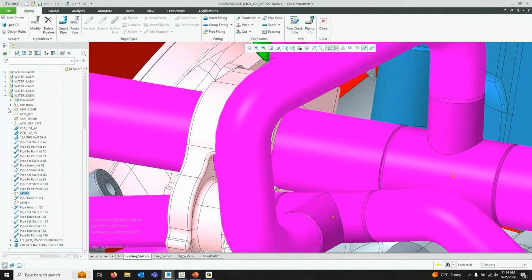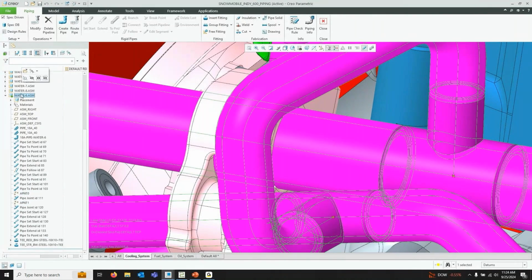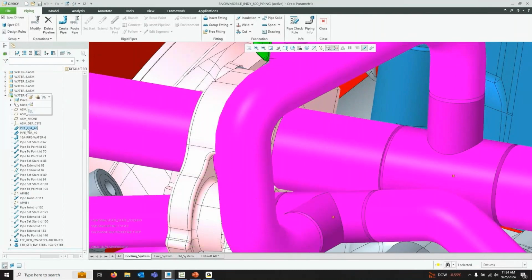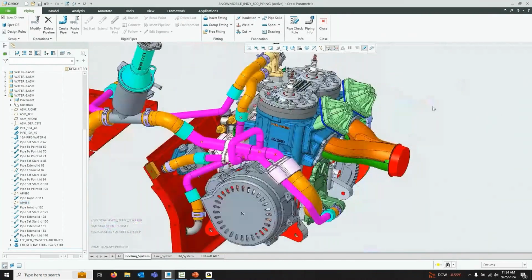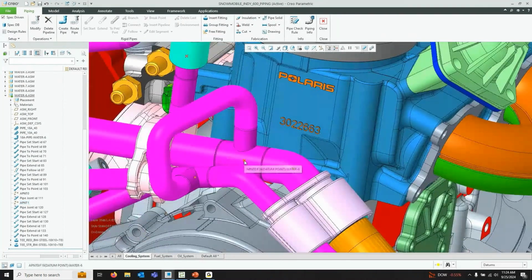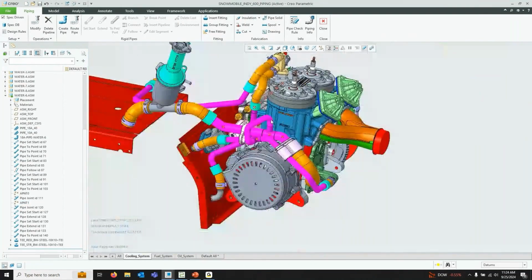Yes, we can see these points are created as part of this piping assembly. We have the pipeline features or line stock features, the pipe feature itself, the specific segments we created, like 2 port, and then the points are in here. So in that sense, it doesn't really matter if you created them externally, because you could just select them, or you can create them inside of this tool.